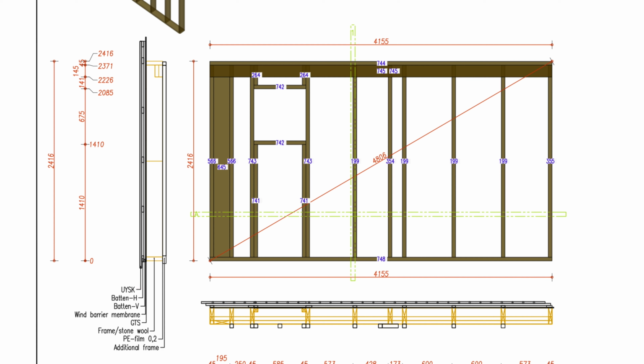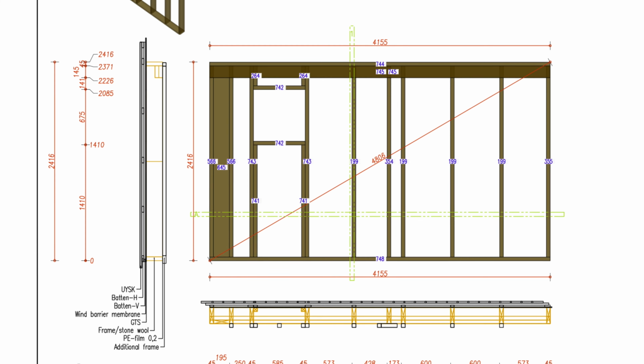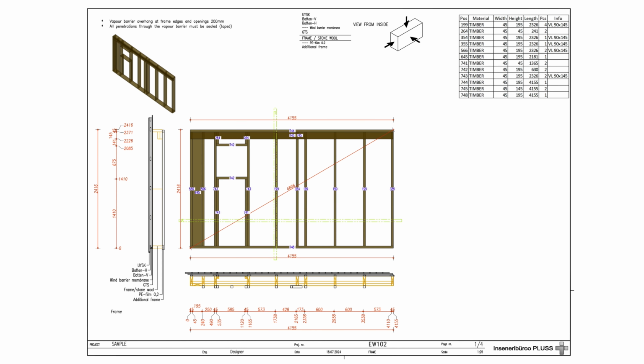Looking at the given drawing at the horizontal section, we see the frame posts and related wooden elements in brown. The section also includes the elements that this structure will come into contact with later. These are shown in black. The drawings of the additional elements can be found on the following pages. In any case, a 3D view helps to better understand a particular detail element, but in the case of very simple details, there is simply no need for this.